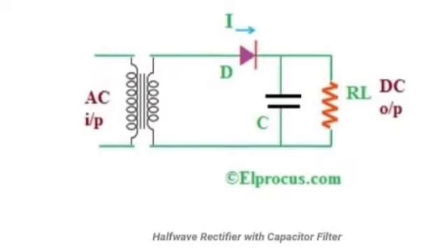Nakakontain ang mga capacitor sa isang metal container that is a dominant ground para sa dalawang capacitors. For additional info lang, ang rectifier is a system na nagko-convert ng alternating current or AC into a single path DC. So ito ang sample diagram ng half-wave rectifier with capacitor filter. Sabi nga, whenever a changing DC is given to any type of electronic device, then it may not function correctly at maaaring ma-damage. So dito, kakailanganin si capacitor filter to get the DC smooth.